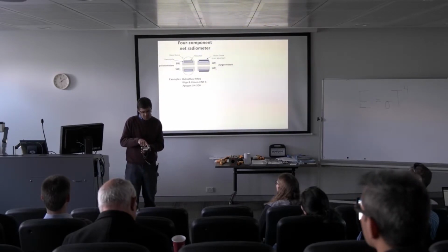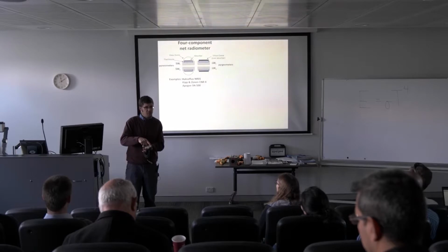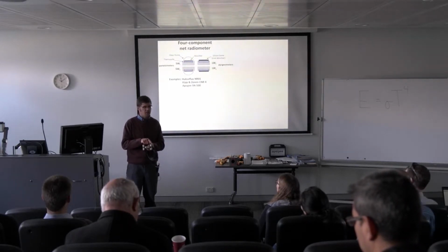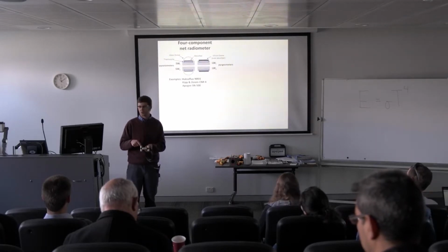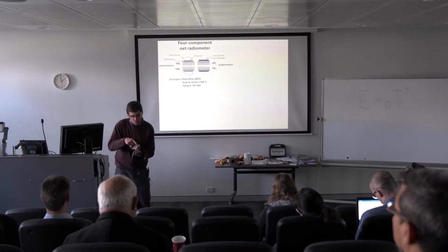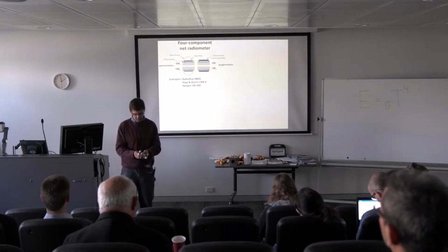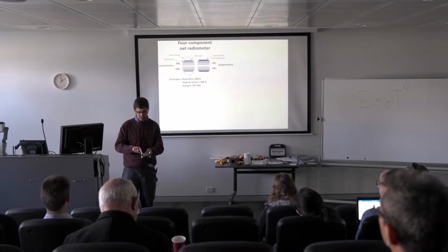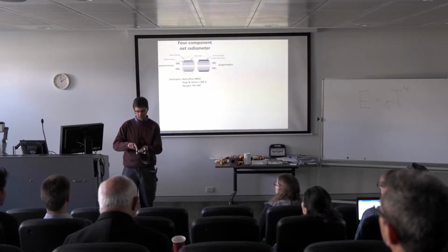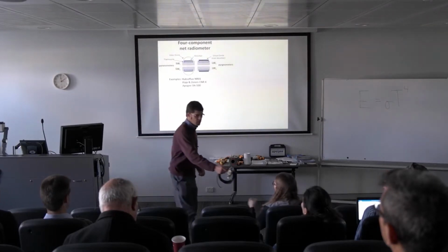So this sensor here with the white diffuser on the top is the upward-looking pyranometer. I know I just said they typically have glass domes. This one doesn't have a glass dome. It has an acrylic diffuser, which is also transmissive to the shortwave wavelengths. The bottom pyranometer is a glass window. That's this one. Then the two pyrgeometers have flat black windows that are made of silicon. They look the same, up and down. So you're welcome to have a look.